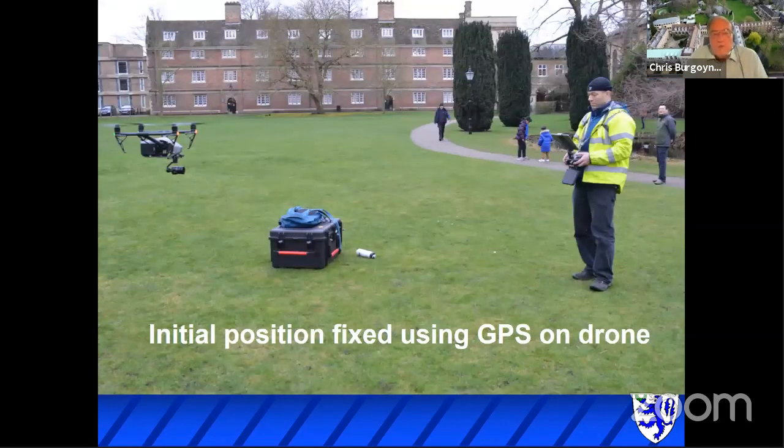So here we are. This is Michael with his drone in the middle of the paddock. And we fix our initial position by using the GPS on the drone. So the drone is flying here, the camera is beneath it, and it's got a GPS receiver built into it, and it attaches the position that it takes the photograph to each photograph. But it's where it thinks it is.